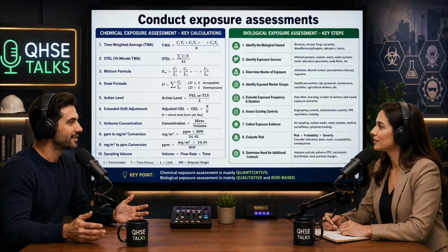And that brings us full circle to you, the listener. Whether you're prepping for the ASP exam or actively managing exposures in a chemical plant, we have covered a staggering amount of technical ground in this edition of QHSE Talks. We've navigated the bureaucratic friction between OSHA's economic PELs and ACGIH's strictly scientific TLVs. We've unpacked the rigid physiological rules of the 15-minute STEL and conceptualized the compounding biological burden that makes adjusting TWAs for 10-hour shifts so critical.